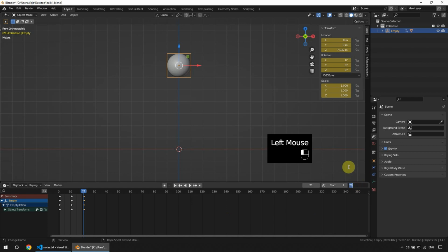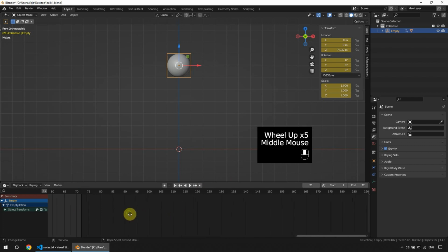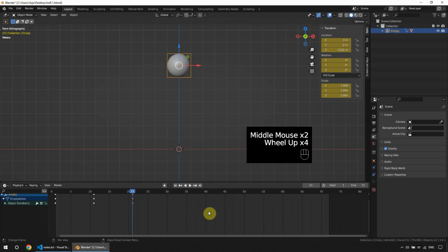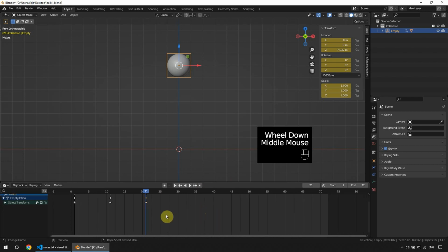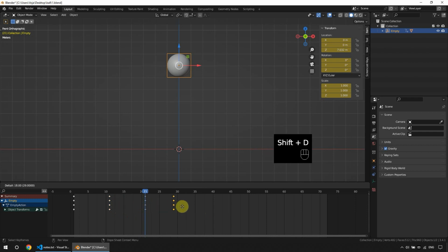And I'm also gonna change the N here to 72 so that the animation is 3 seconds long, so 24 frames per second. Okay, so the next step is, and let me actually scroll up just to see this more clearly here. So the next step is for the ball to be at the bottom, so select these and Shift D and move them, but not to 30 now, but less, because we need to have less and less space now between the ups and downs.